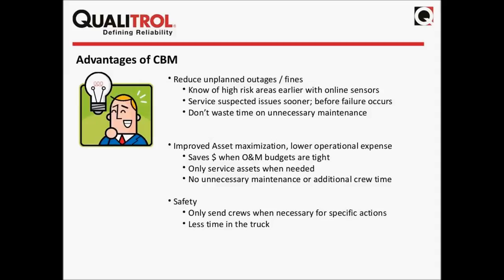You know the areas of high risk earlier with online sensors like the smart breather, which are going to continuously regenerate themselves, so you don't have to send somebody out there to look at it all the time. You can service suspected issues sooner before failures occur. And you don't have to waste time on unnecessary maintenance, again, just going out there and checking a list. I checked this, I did that, when half of the time there's no issue to be seen.